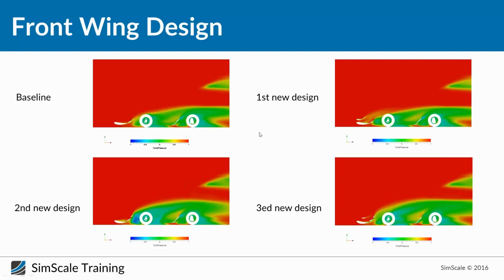Of course, here by adding these cascade elements, we can see that we also have separation of the flow on top of the wing, because we have a suction effect here, in between the cascade elements and the front wing, and this acceleration will take more air upward, so that's why we can see that we have separation over here. And if we move to the next car, where we have the 3-element wing,